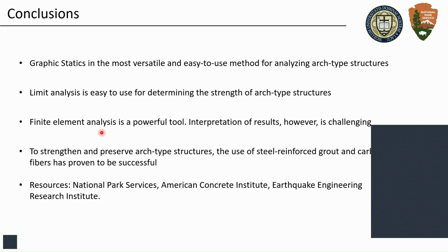To strengthen and preserve arches, the use of steel reinforced grout and carbon fiber has proven to be a successful technique. So when you face similar situations, you know where to look. And resources: the National Park Service and the American Concrete Institute have plenty of information on retrofitting any type of structures. The Earthquake Engineering Research Institute, if you end up dealing with seismic or arches or historic structures in seismic regions, is a good resource as well.